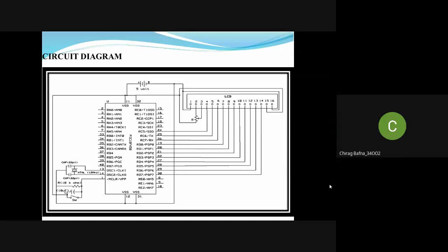There are two very important registers inside the LCD. The RS pin is used for their selection as follows. If RS equals 0, the instruction command code register is selected, and it allows the user to send commands such as clear display, cursor at home and so on. If RS equals 1, the data register is selected, allowing the user to send data to be displayed on the LCD. After that, we can see the LCD display.